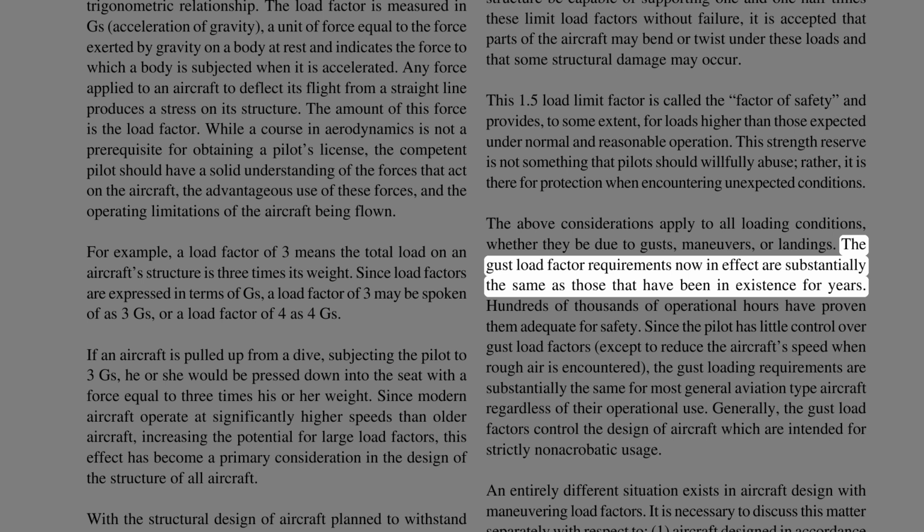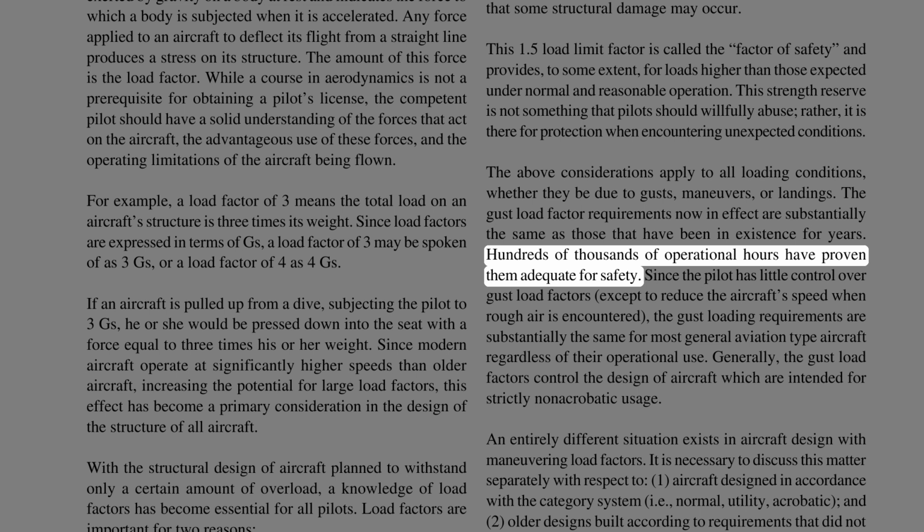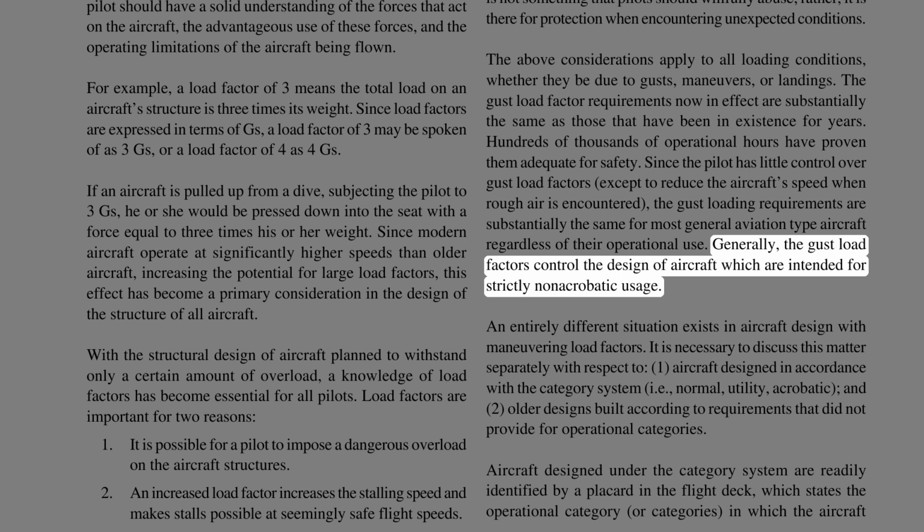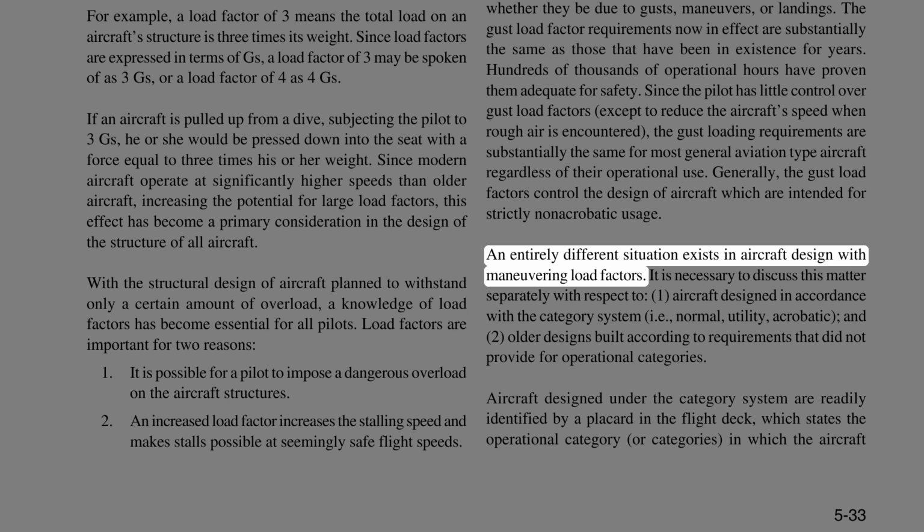The gust load factor requirements now in effect are substantially the same as those that have been in existence for years. Hundreds of thousands of operational hours have proven them adequate for safety. Since the pilot has little control over gust load factors, except to reduce the aircraft's speed when rough air is encountered, the gust loading requirements are substantially the same for most general aviation type aircraft regardless of their operational use. Generally, the gust load factors control the design of aircraft which are intended for strictly non-acrobatic usage. An entirely different situation exists in aircraft design with maneuvering load factors.